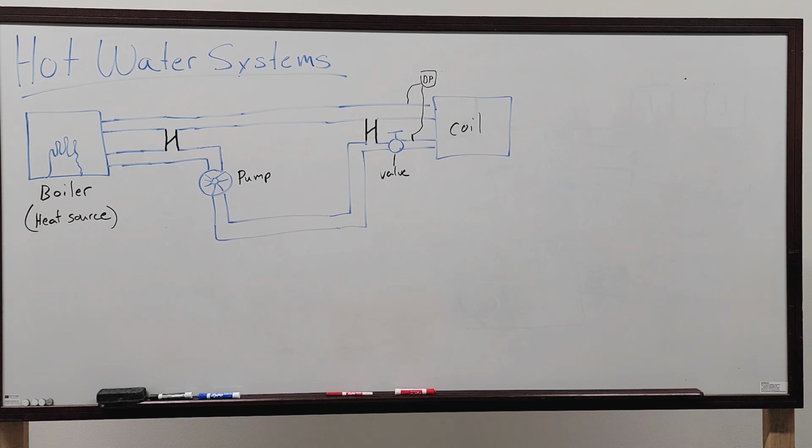Yeah, it's pretty much... where was I going with all this? Okay, so in a hot water system, like I said, there's differential pressure, which is maintained by a valve. Most systems that have a three-way valve, like Holden was talking about, are not maintaining differential pressure. They may be maintaining differential pressure as well as having a three-way valve. That's when they get real fun. But most of the time they do not, because they're constant flow.